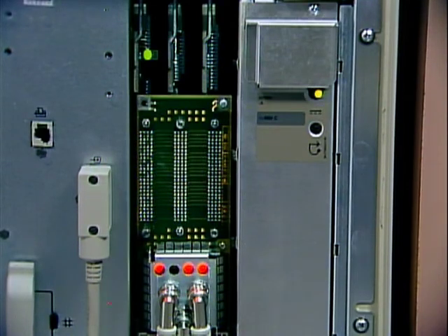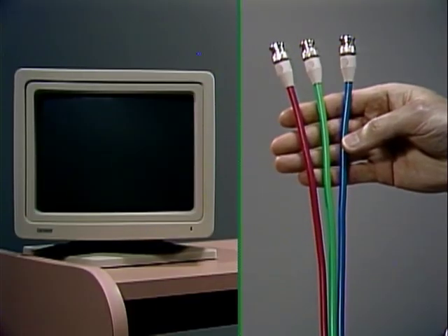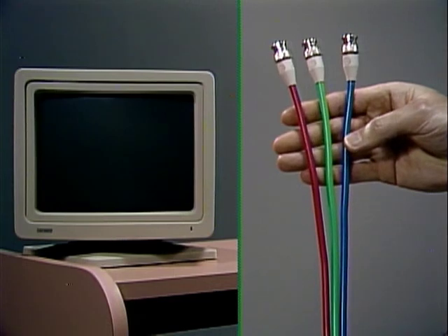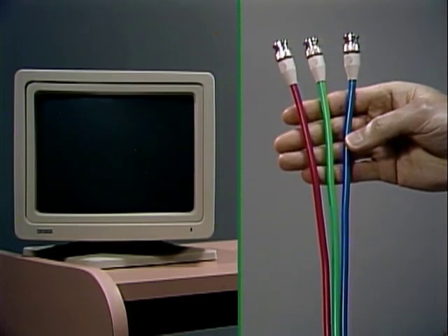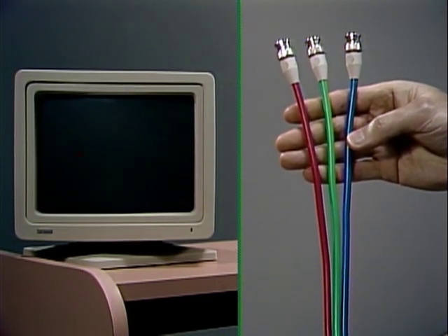To do this, first observe the green indicator that is mounted on the graphics base module. If it is lit, no error has been detected by the PST. This indicates that the graphic modules and front plane are probably good. If you detect a problem with the subsystem and the green LED is on after the PST has completed, the problem most likely exists in the monitor or cable.